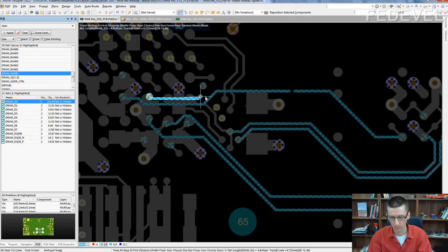Hug and push. Stop at first. Auto route, auto route. Ignore. Ignore is I can go through. See? I use ignore and I use this one, walk around. Usually I use walk around obstacles by the end of the design. At this stage, push obstacles is the best option.